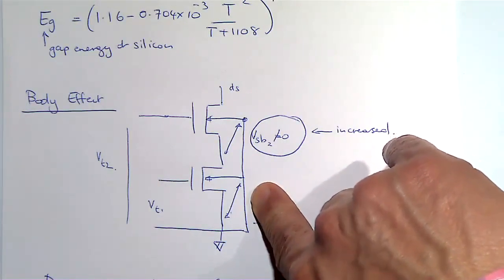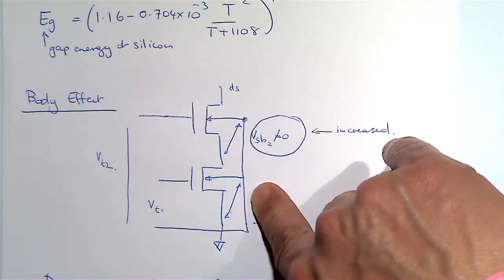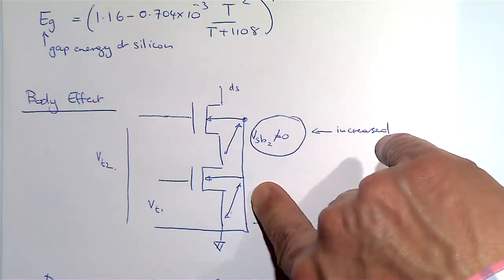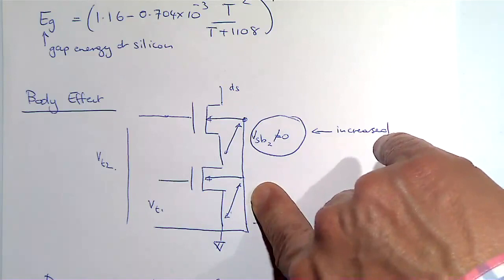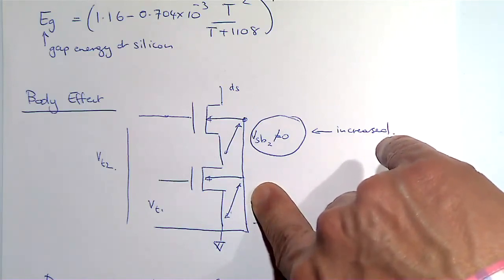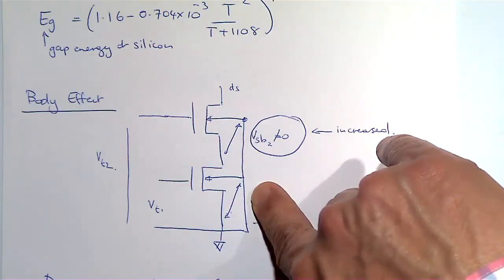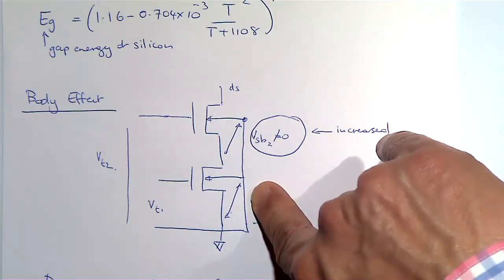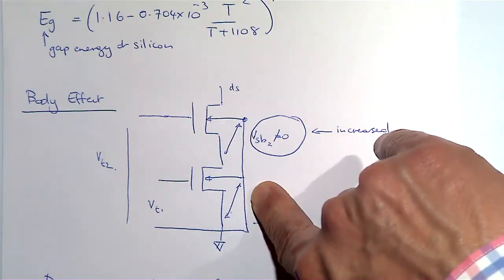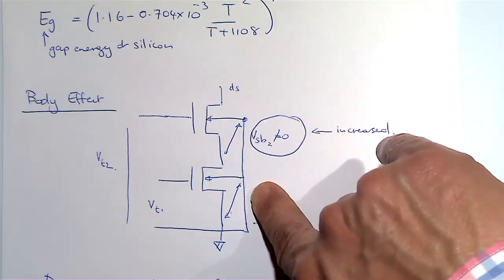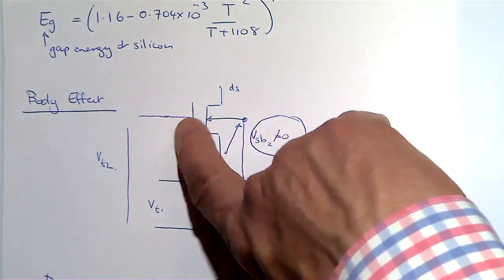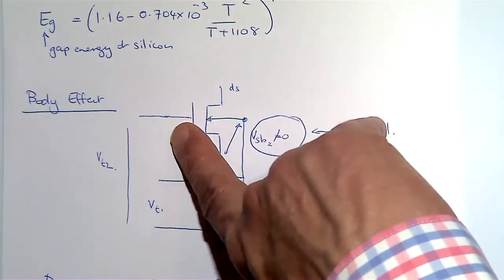The output of a power amplifier at low frequency is V squared on RL, where V is the voltage that you can actually swing, right? So if you've got a transistor which is, say, for example, got a 1 volt maximum, if you put 2, right, you've got 2 volts that you can actually swing, but what happens is, you can't actually go all the way up to 2 volts because all of a sudden your threshold voltage starts to increase.